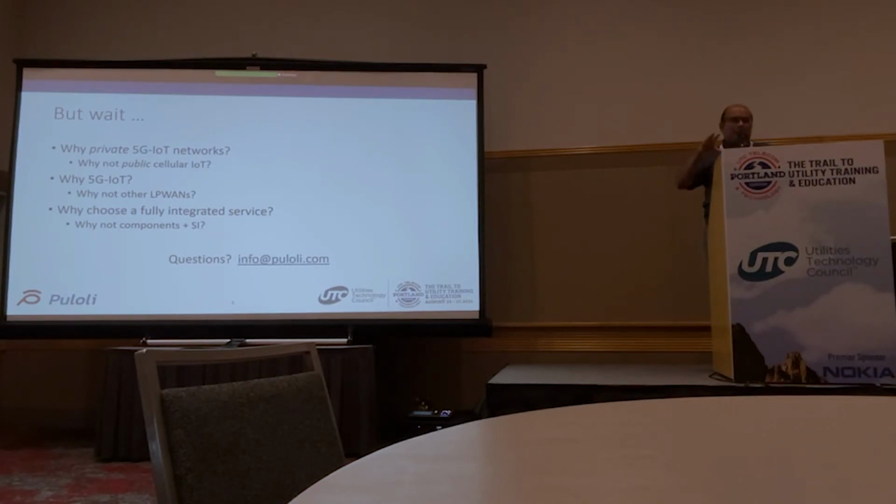If you ask me what the physical layer link throughput is, it's on the order of 100 kilobits per second for NB per 200 kilohertz carrier, and about 500 kilobits per second for Cat-M at the physical layer. This depends on the coverage conditions and a bunch of other factors, but that link level throughput doesn't mean anything in terms of use cases. You can have tens of thousands of devices on NB-IoT, a few 200 kilohertz carriers, if you do a telemetry profile, and if you do the edge compute and the wireless link optimization correctly. However, just to repeat myself, if you want a sustained guaranteed throughput link, you need to go to proper broadband. IoT is not your solution.